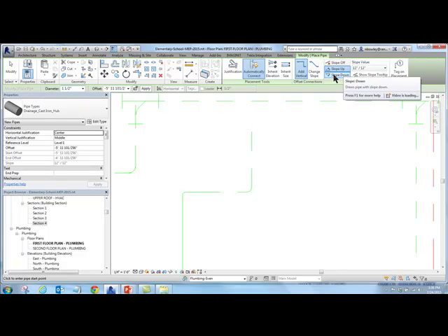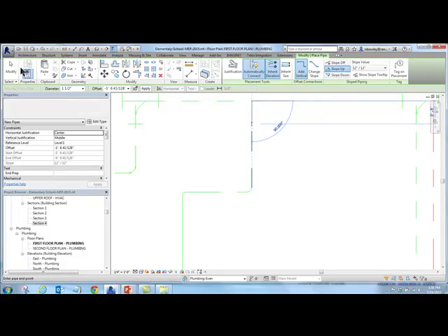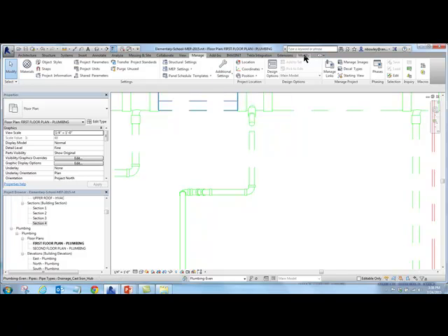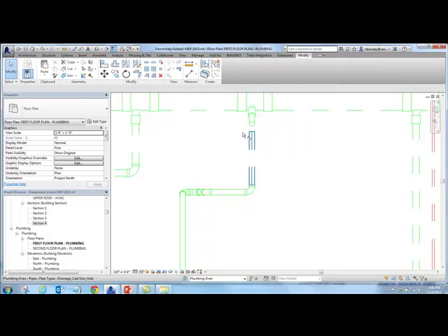It should have been slope up. That seems right. Oh, I don't think I was inheriting the elevation, is what I was missing. So there I've got a rolled T, and if I turn it to fine detail level, you'll see the rolled T. And then you just have to fillet them together or trim and extend to corner.